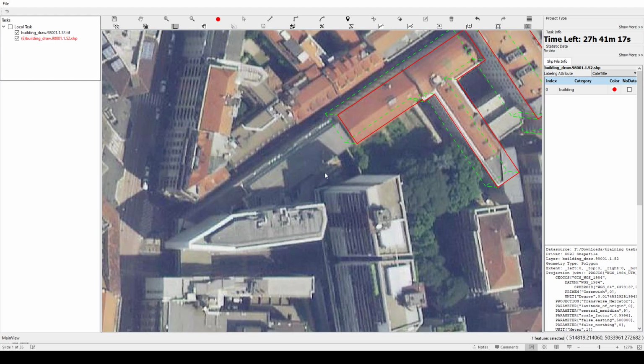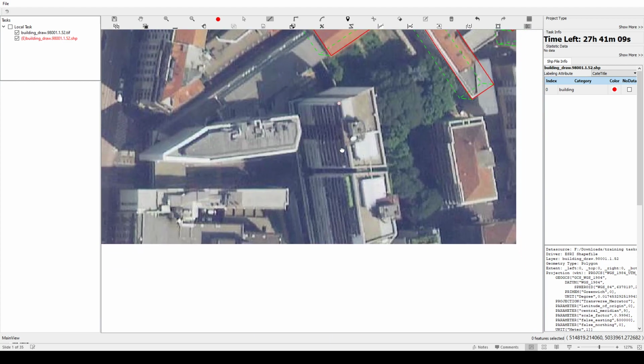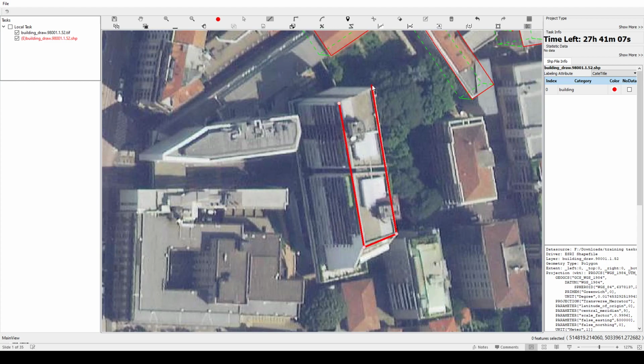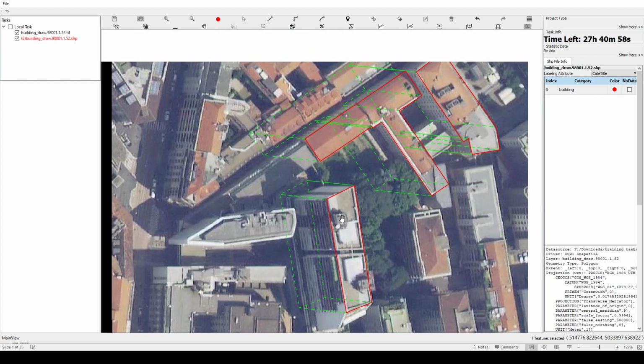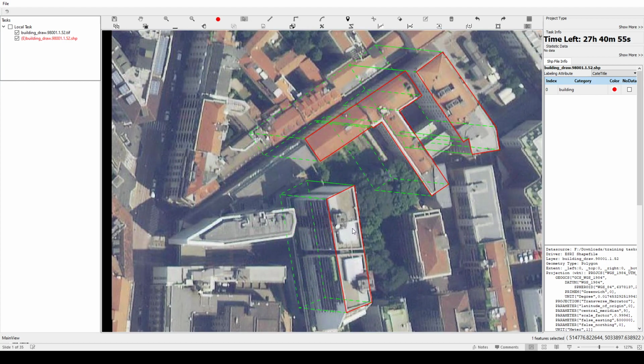For example, if this building has a different sidewall, okay, for example on this building, guys, if you see this dragging here, you can see it dragging, right? So what you need to do is select this, Control Q. Okay, this will separate this from these buildings. So once I press Control Q, it will have its own vector. You could make it as a separate one.